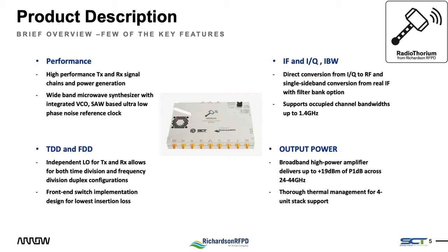Two microwave wideband synthesizers from Analog Devices provide the main building block for our LO generation circuits. They allow implementation of fractional-N or integer-N PLLs, have integrated VCOs, and support reference input frequencies up to 600 MHz. They could be disabled or bypassed, allowing for external LO injection for those use cases where lower phase noise is required.